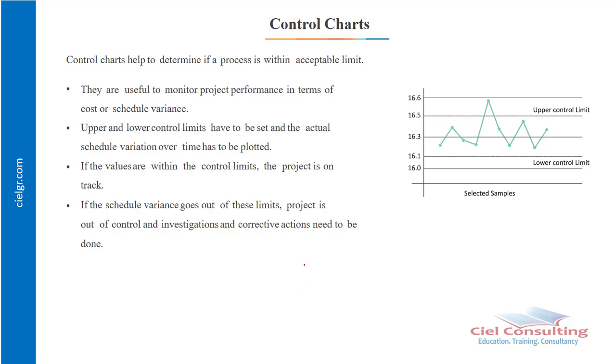So let's say, for example, we're into the manufacture of plastic chairs, and we have a measurement that the thickness of our plastic chairs at every point in time should be at least 5 mm. So in the course of the manufacturing, don't forget 5 mm is the expected. So that's the mean. This is essentially what we're expecting to get. But then we set up what we refer to as an acceptable deviation. If the measurement is not exactly 5 mm, is there a range that is still acceptable? So we can simply say, okay, 5.5 is still acceptable.